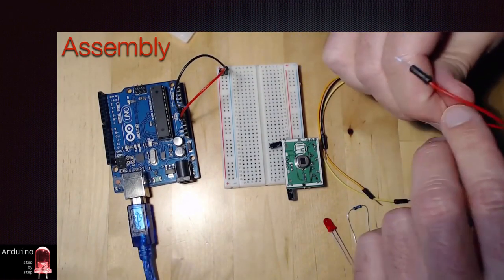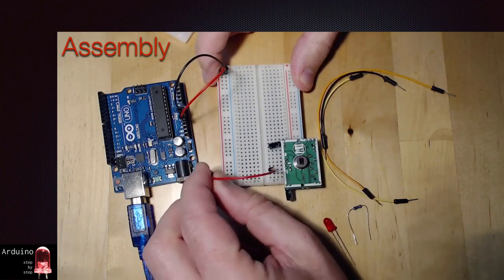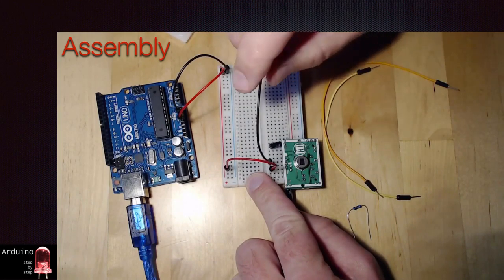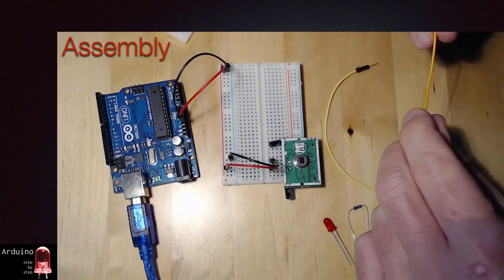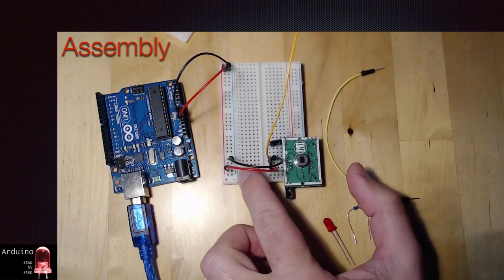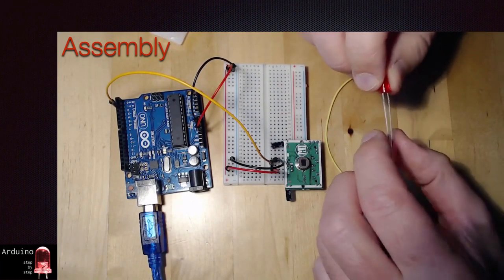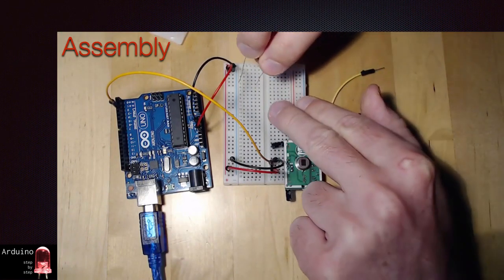Next, we'll connect power from the sensor to the positive voltage line on the breadboard and do the same with ground. Take a yellow jumper cable and connect the sensor's signal output pin, the middle pin, to digital pin 2 on the Arduino. Now let's move on to connecting the LED. We'll start with its protective resistor. We'll connect it with one end to ground on the breadboard.